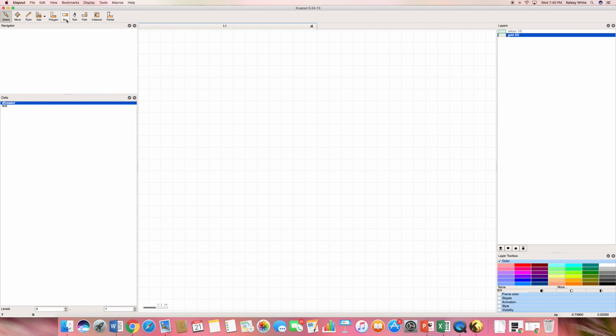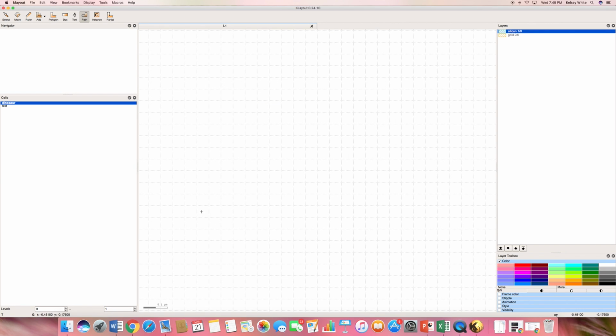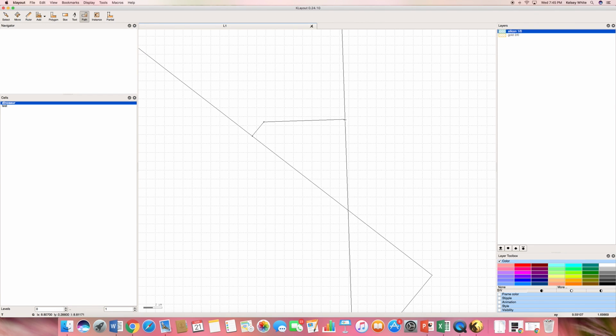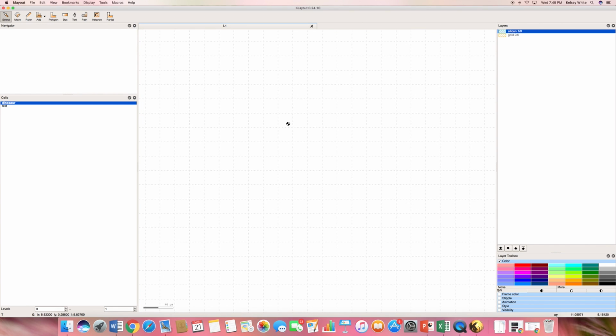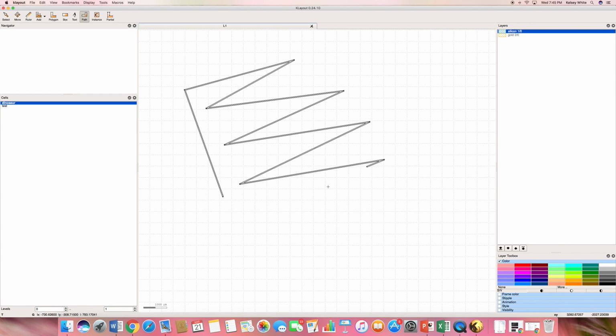So now I have this other cell, and I have to click which layer I want to put it on. I'm going to create a path, 50 microns. I was so zoomed in. Okay, I'm going to zoom out a bunch. So I'm going to create a path, 50 microns. Okay, it's a fine path. I can move it around. I can do whatever I need to it.